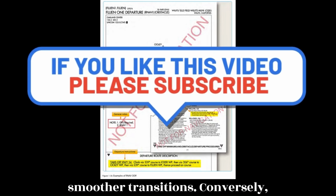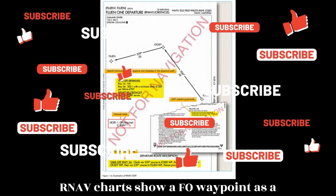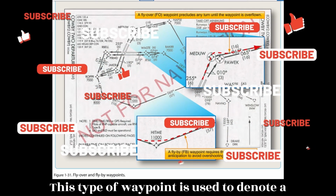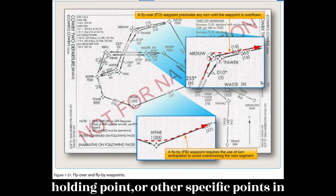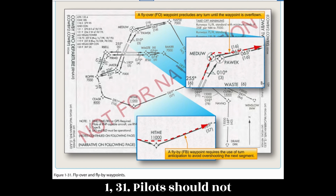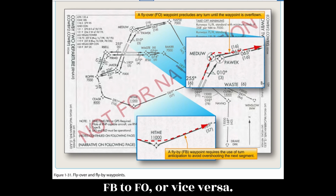thus providing smoother transitions. Conversely, RNAV charts show a FO waypoint as a four-pointed star enclosed in a circle. This type of waypoint is used to denote a missed approach point, a missed approach holding point, or other specific points in space that must be flown over. Figure 1.31. Pilots should not change any database waypoint type from an FB to FO, or vice versa.